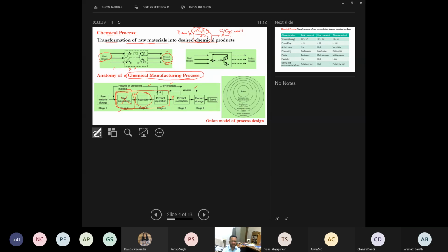So finally what will you get? So after having some minimal residence time, it has to be sent to the digester or reactor vessels. Here only the complete reaction takes place. So you have to maintain the process conditions in the digester. You have to have a series of digesters in the process plants. The temperature would be around 120 or 125 degrees centigrade. It has to be operated at a pressure of 6 to 8 atmospheres. You have 4 different long, tall digesters. It is digested properly with NaOH.